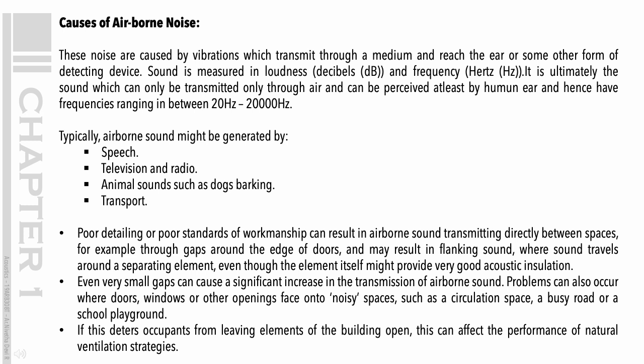Poor detailing or poor standards of workmanship can result in airborne sound transmitting directly between spaces, for example through gaps around the edge of doors, and may result in flanking sound, where sound travels around a separating element, even though the element itself might provide very good acoustic insulation. Even very small gaps can cause a significant increase in the transmission of airborne sound. Problems can also occur where doors, windows, or other openings face onto noisy spaces, such as a circulation space, a busy road, or a school playground.